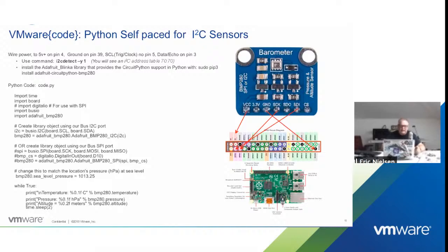So that's setting that in the BMP280 object. So it'll use that to normalize what it's going to print out for you. So if you're living in Denver, which is a mile high up, your barometric pressure is going to be different, and it should probably say not sea level, but ground level, so that you have a normalized pressure for your ground level. And then now I just sit in a loop while true, print, and it's a float, BMP280.temperature.